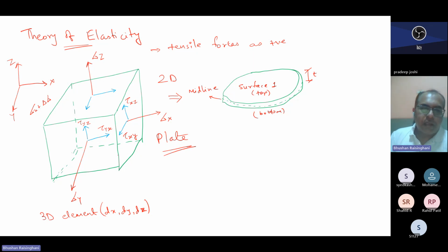Right. So tangential stresses are getting generated, and these tangential stresses we are neglecting if we are using a plate element. And in thin shells also, plate theory is valid, but at the edges and also at locations of cutouts, plate theory does not work.